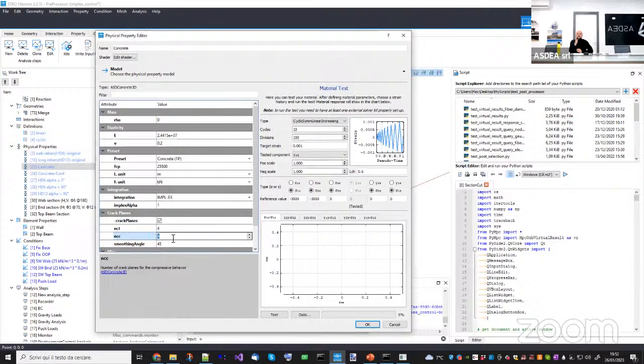I simply do that by comparing, for example, the principal stress direction with all the normal cracks by taking the dot product, and the maximum dot product will tell me what is the closest normal. Now think about repeating that for thousands of planes; of course, it can take a little bit. So 4 by 4 is fine, because I think it was a total of less than 64 planes, because there are the poles, which are singular points. But yeah, let's say this one is a good number. Do not exaggerate with that.